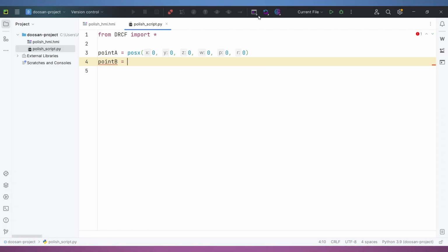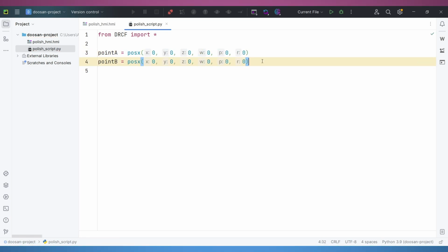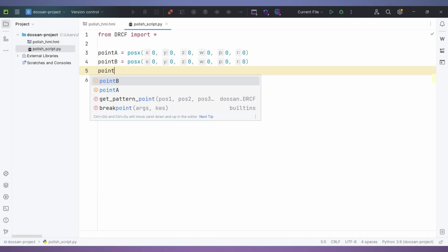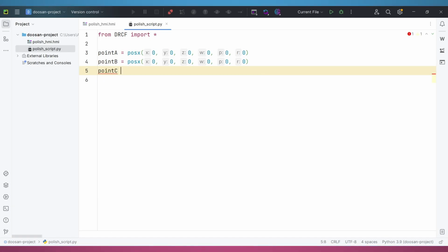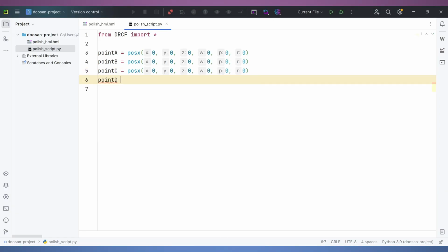In this tutorial demonstration, we are using global variables to define the robot positions. In a real-case scenario, it would be better to define those variables as system variables inside the robot task editor. System variables always keep their last values, and store their values even after the robot program is stopped.